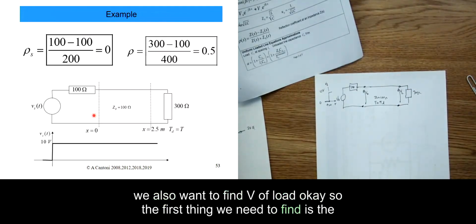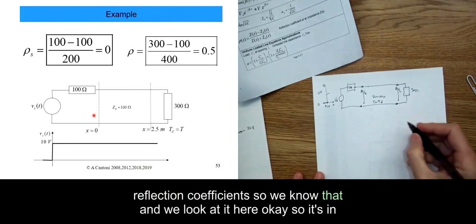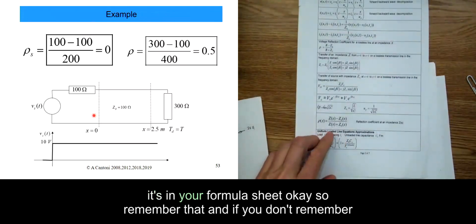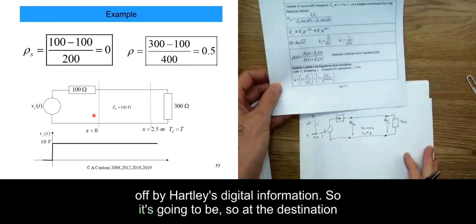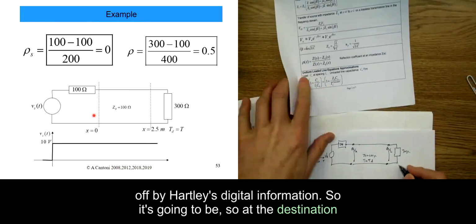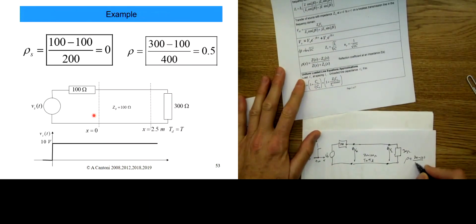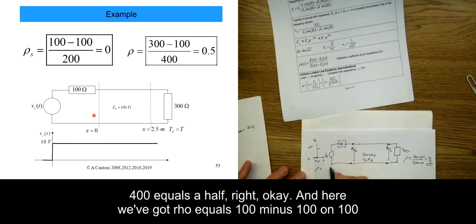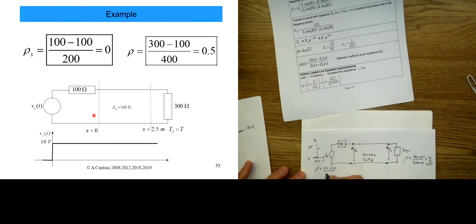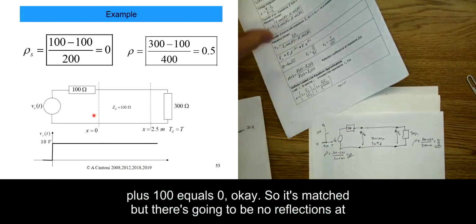The first thing we need to find is the reflection coefficients. We're always tackling these problems by finding reflection coefficients. It's in your formula sheet, so if you don't remember it off by heart, just look in the formula sheet. At the destination, rho is 300 minus 100 over 300 plus 100, which is 200 over 400, equals a half. And here we've got rho equals 100 minus 100 over 100 plus 100 equals 0. So it's matched, and there's going to be no reflections at the source.